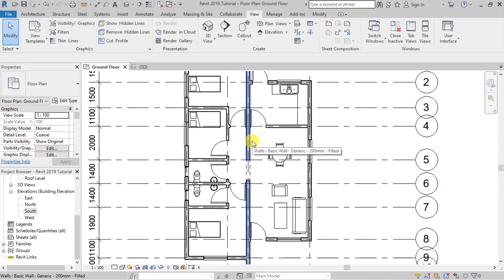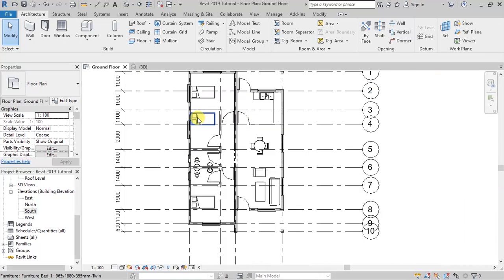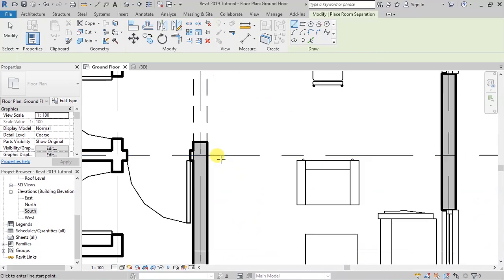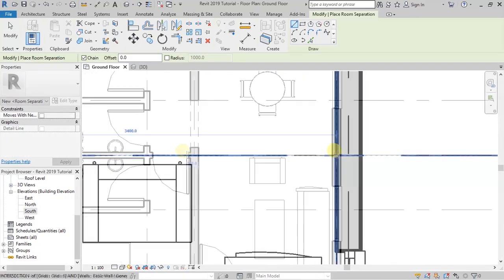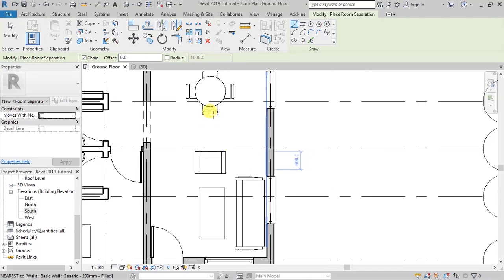And I want to look at the architecture tab here. I want to put some room separators where we have like this big open space here that is being shared by our dining area and the sitting area. I want to use this room separator here. Click on room separator, and I'll draw from this to this wall. Click on escape so that we have separated these two rooms.